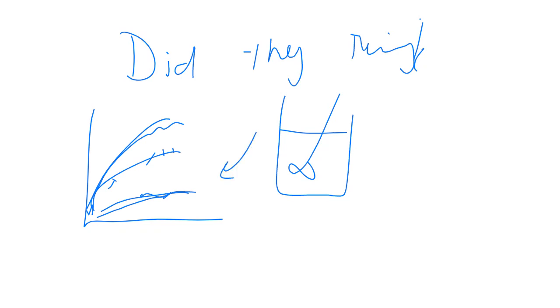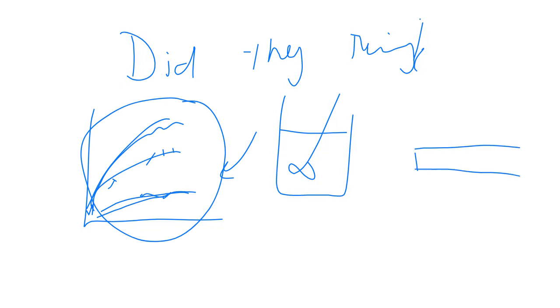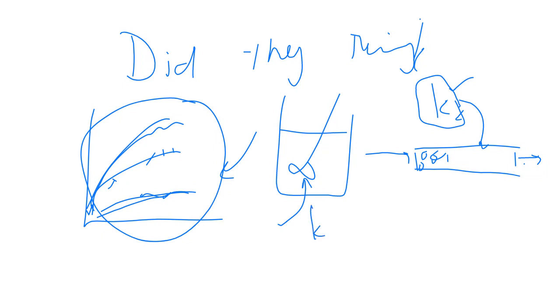And now you are going to use that information to design a reactor that's got a completely different shape. So where the Kc value may be the same, it may be different because the shape is completely different. You want to apply it in a plug flow reactor. This was in a batch reactor. The Kc value in a batch reactor is a completely different shape than the Kc value which follows the Teunis-Kramer relationship in a packed bed reactor.